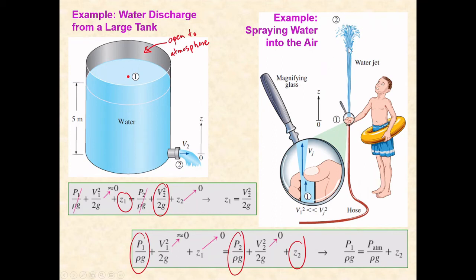It's quite obvious that the velocity V2 equals 0 because it stopped, and Z1 is used as a reference point, so Z1 becomes 0, and Z2 is an elevation, the maximum point from Z1. So basically we can know how high the water will go. So Z2 has some value, Z1 equals 0, and then P1 and P2.